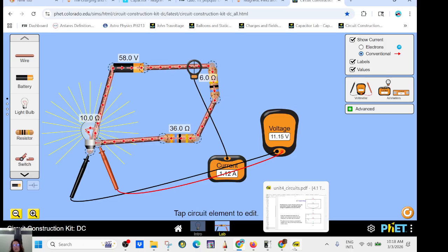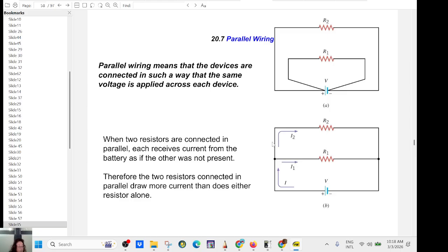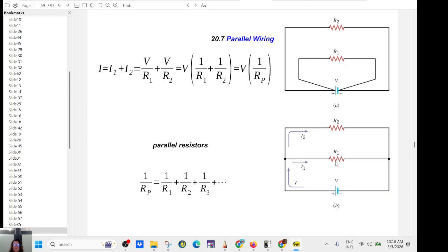So instead, we don't do that. We do it as a circuit in parallel. In that case, everyone is happy. No one complains because they all get the same voltage. They both have the same voltage drop across, and the current that they get depends on their appetite, depends on their resistance. So now they are not complaining anymore.